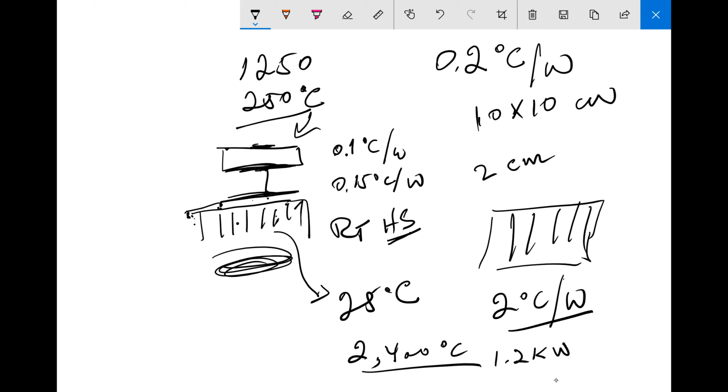If indeed you try to keep this slab here at 25 degrees centigrade, for example, you can use liquid cooling. Pass a cool liquid through some heatsink for liquid, attach it here, and then lower the actual ambient temperature. So you have a larger permissible temperature drop.